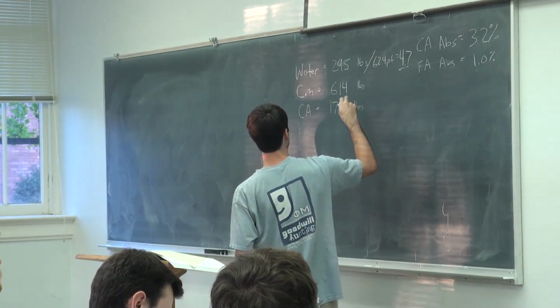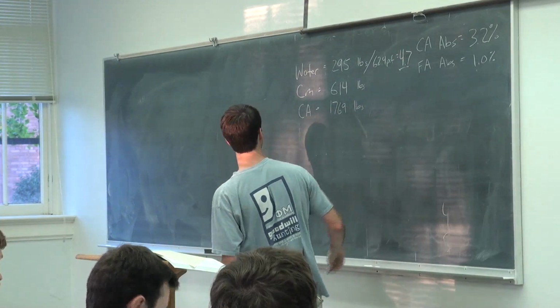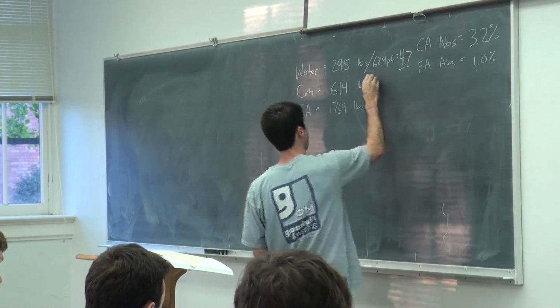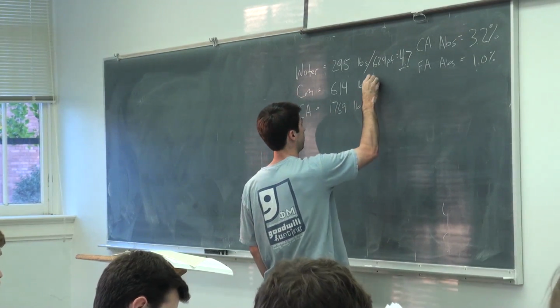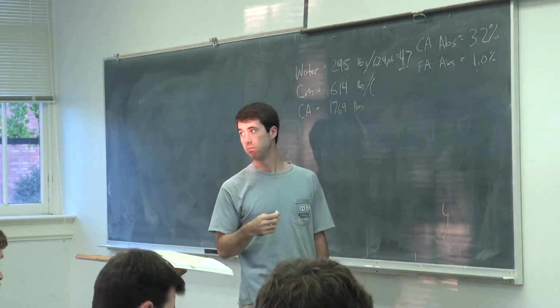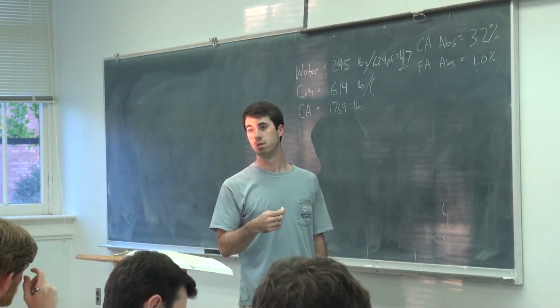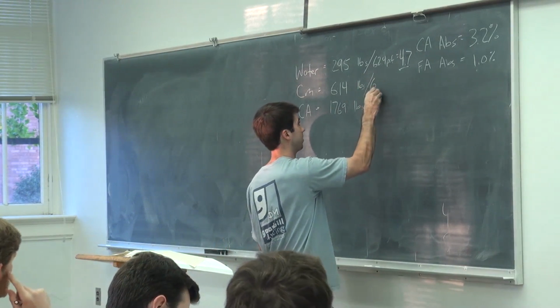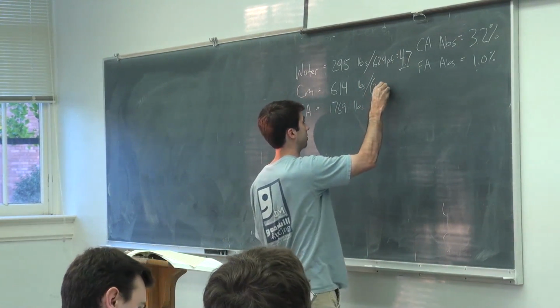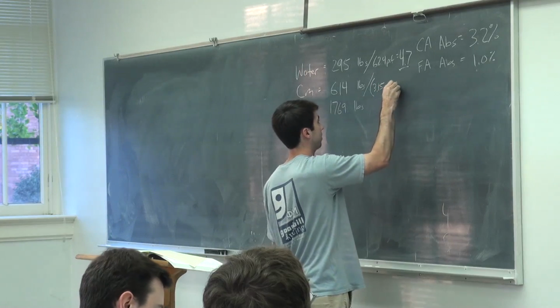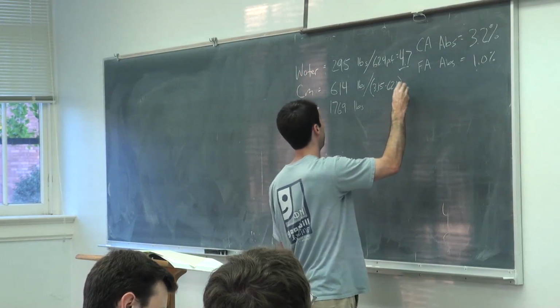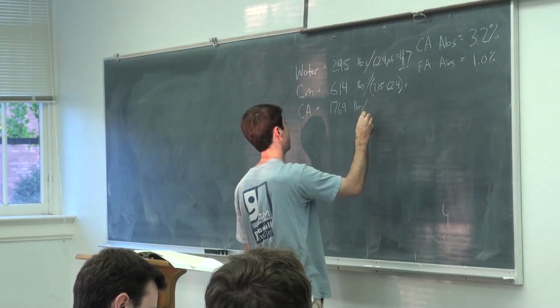Alright. And then for the cement and coarse aggregate, we know there are specific gravities. Specific gravity of cement, anybody? 3.15. So just 3.15 times the 62.4 to get the unit weight per cubic foot. What's that number?